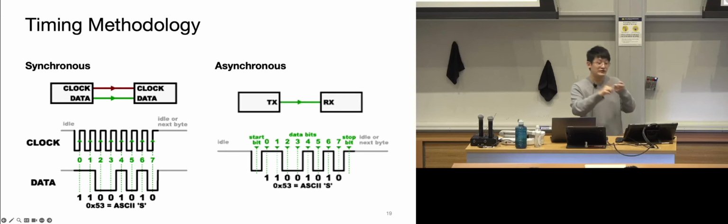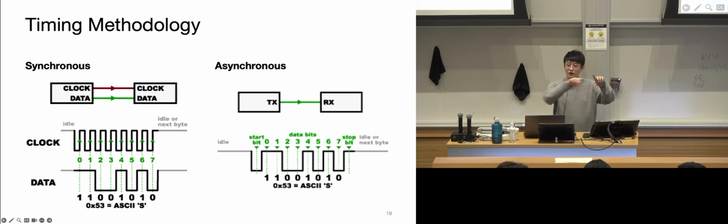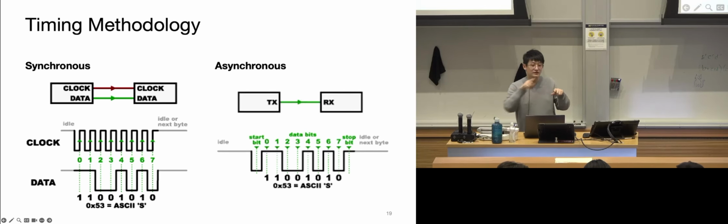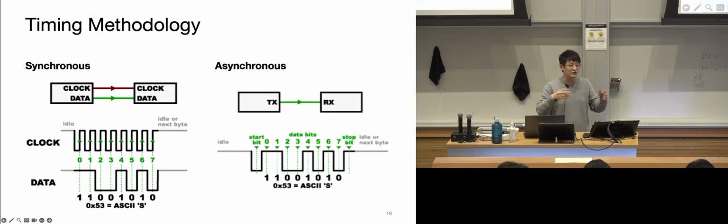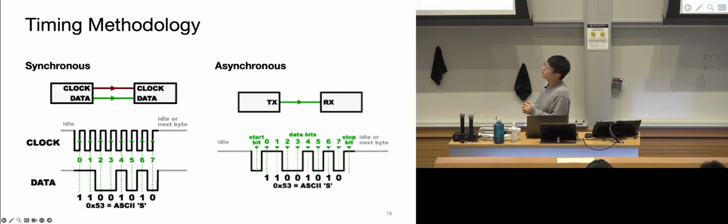Oh, good question. Yeah, good point. That's why in PCB design, if you have multiple chips on the PCB, you always try to have those parallel wires go side by side so that they roughly have the same length. Good one, yeah. Otherwise, chances are if it's a super fast clock, you might have these issues. Yeah. Any other questions?